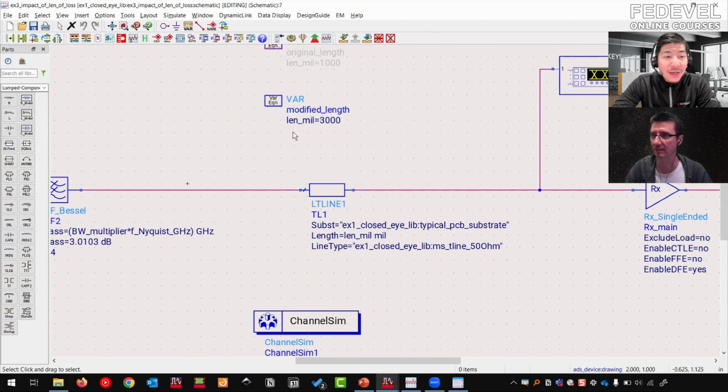Now, my advisor, Eric Bogatin, always asks me, Tim, we have to practice rule number 9. What do you expect the loss to be? And here is where we calculate using our rule of thumb. The rule of thumb here is 0.1 dB per inch per gigahertz.